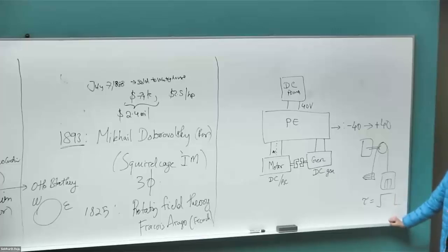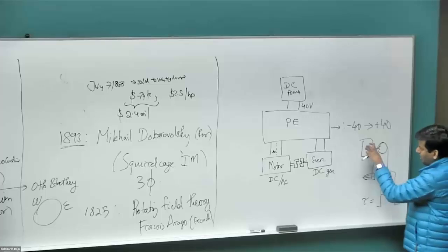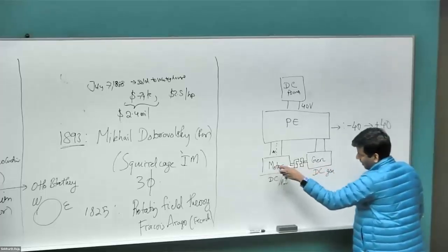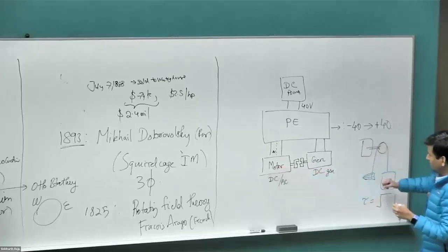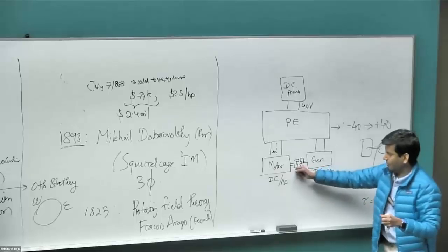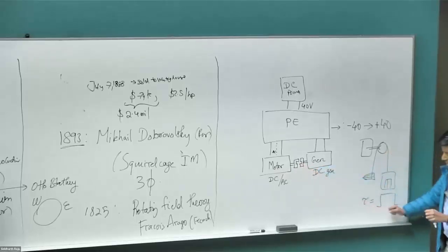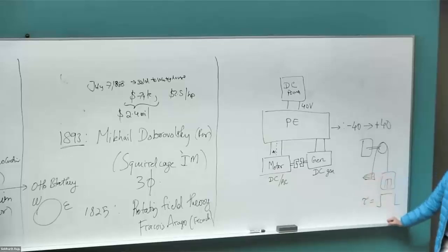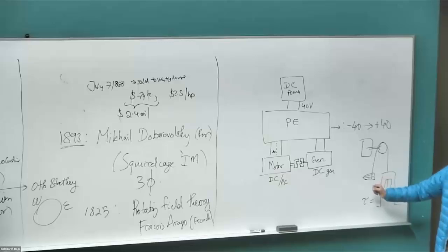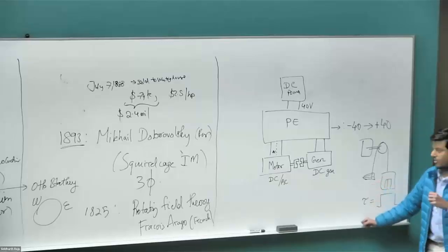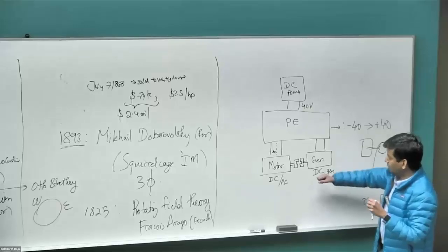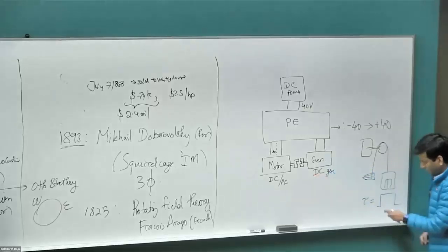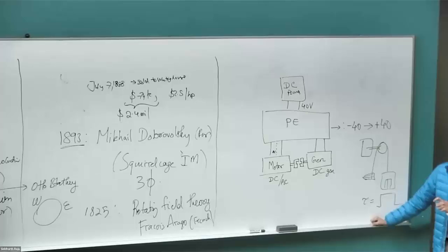So what we want to be able to do in the lab is we only have this motor in our lab, and we want to be able to create scenarios on this motor shaft, same as what would happen in the real world, where the torque changes suddenly, increases, comes down, goes up, comes down. 5 people can get in, 2 people can get in. The speed should remain the same irrespective of how many people are on the elevator, otherwise it will become an unpleasant ride. So in the lab, using this generator, we are going to create these different torque profiles on the motor.